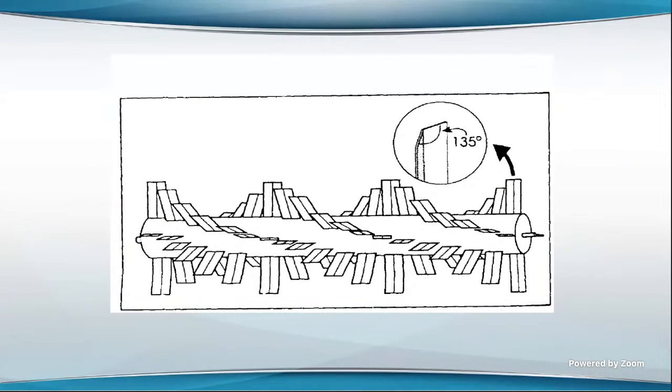We did a lot of work on mechanical aerators here in Auburn years ago because the farmers were wanting an aerator and they couldn't talk any of the agricultural engineers into working with them. And I finally was just kind of forced to work on those things. And so with the graduate students here, we did a good bit of work on these things. We got a torque sensor put in line with the aerator shaft and devised a mechanism where we could make all kind of changes in the shapes of the paddle. It's kind of a modular unit, put more paddles on and different arrangements of paddles and different kinds of paddles.